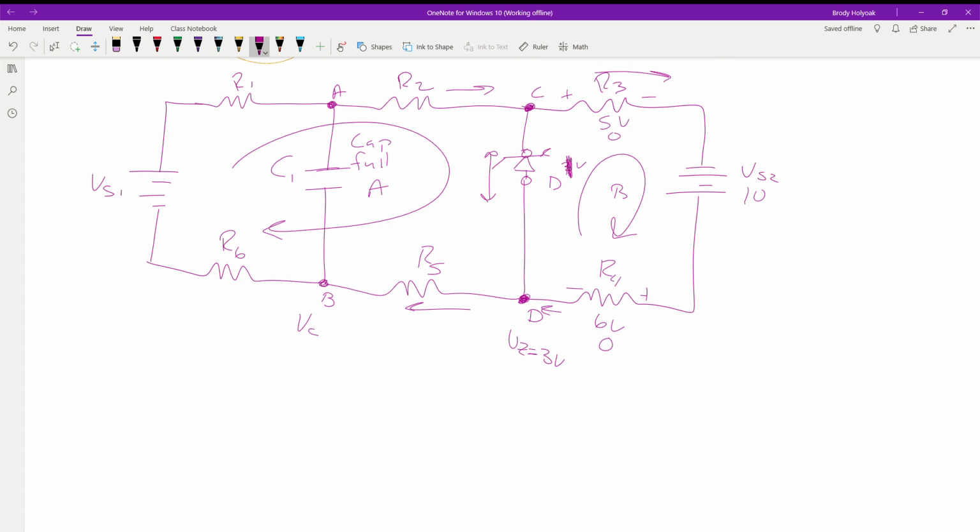Okay, what if we came through and we found out, when we solve for this guy, so remember that the negative part of the diode is here, the positive of the diode is here. What if we come through and we find out, let's say this guy is switched around, and now we have a voltage that goes like this. What's going to happen with that diode? It's only going to drop 0.7. Unless it's a germanium. Unless it specifically says it, assume that it's silicon.